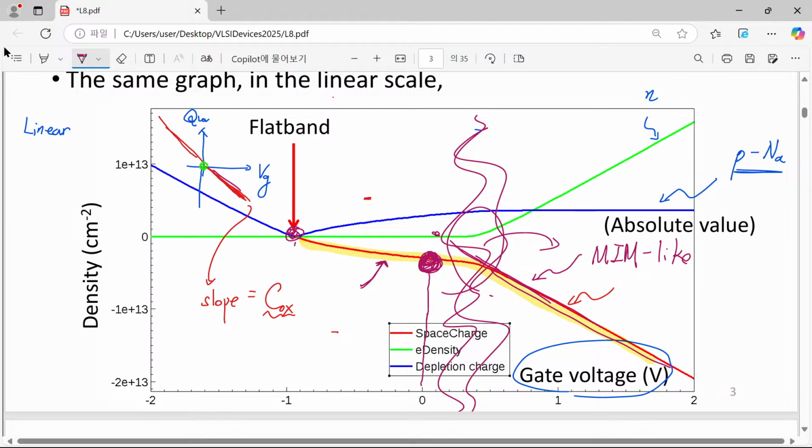So this is nothing related with the VG equal to 0 volt case, because we have different materials on the top and bottom, and they have different work functions. This work function difference defines this different behavior. So then, since we have two different mechanisms, when we have a look at Qs as a function of surface potential, we also have terms related with the two different parts.